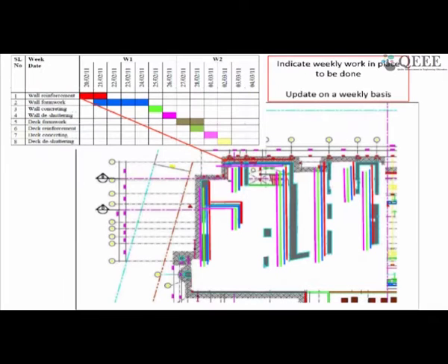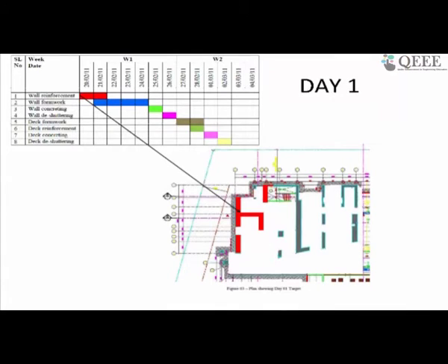plan, I will actually go location wise. I will say on day 1 I will do this. I will transfer my plan to a location in the building. I will not just say quantity and time. I will say quantity, location and time. So before formal LBMS is used, certainly location based planning is used in best practices,